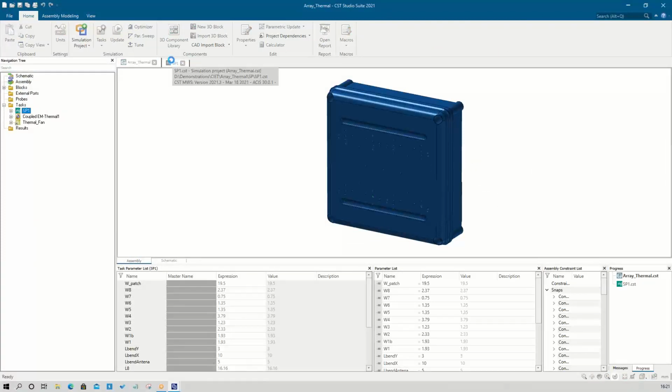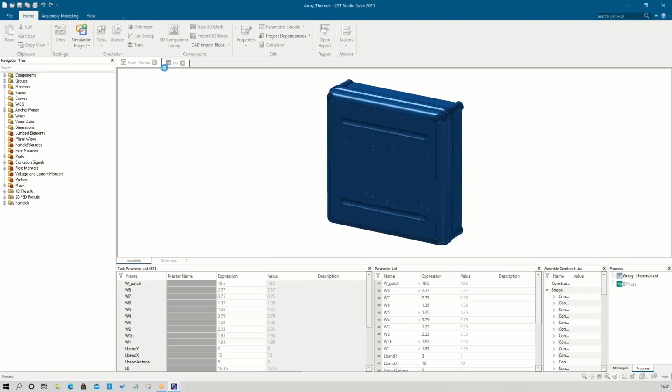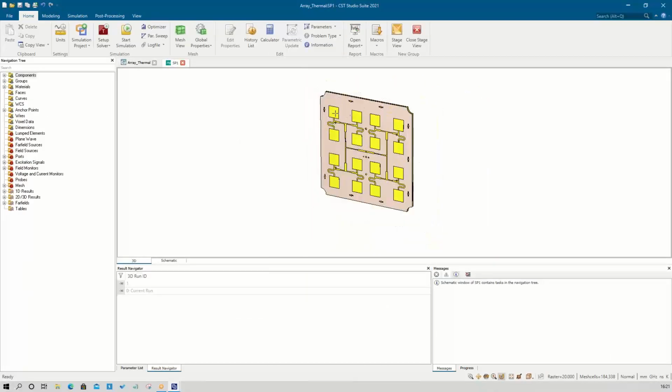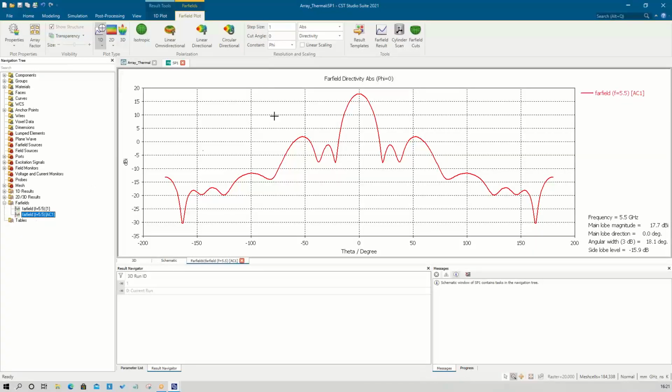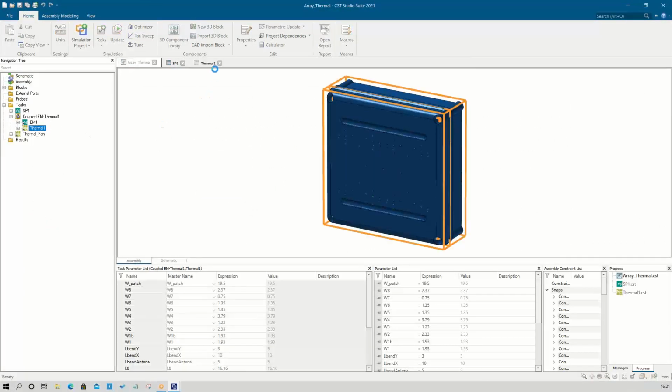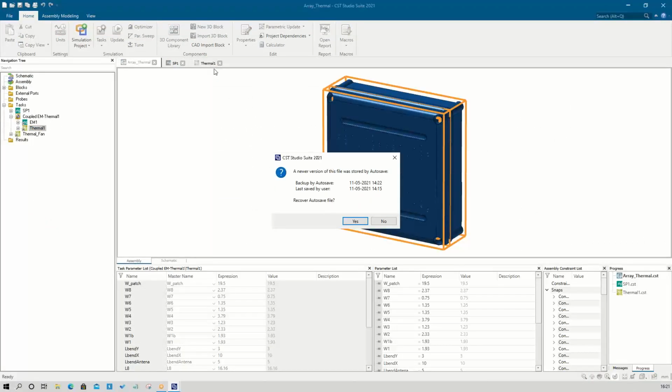So this is the 3D model of that antenna array. I just removed the box just for doing this image. You will get the same result. You can see that complete structure along with this feed. So this complete feed is designed here only. And this is the pattern, around 20 dB gain is there. But I'm not interested only in that, I will be doing this simulation for the complete answers.